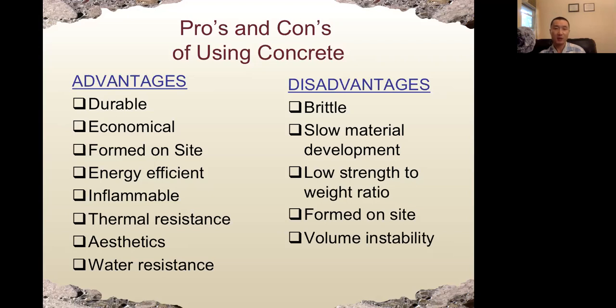Concrete also has a slow material development. We need several days of curing. Curing is the process where we put water in concrete to let the concrete achieve its design strength. So concrete needs several days to achieve its design strength.